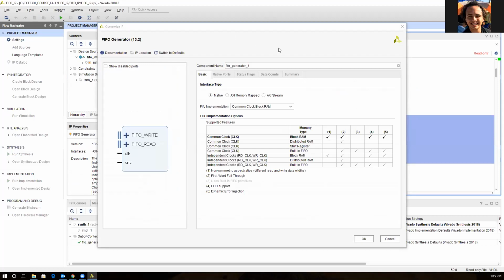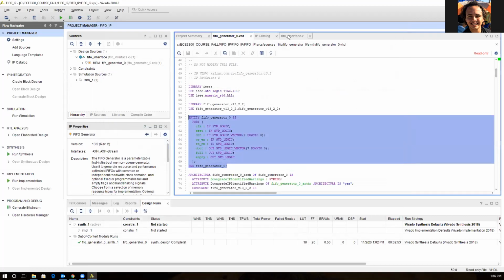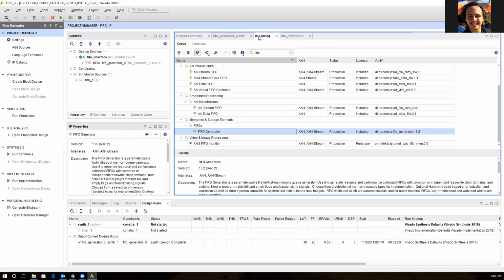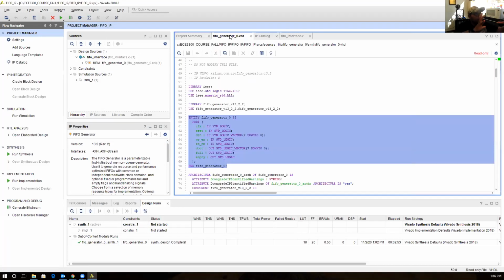If you were to start outside of the IP catalog and then create a block design instead and then add the IP onto the block design? No, that's a different story. You know why? Because you're going to build pieces and connect them together. Still, we are using HDL here, right? What you're talking about is completely different, because you're drawing and placing blocks. Then you have to do something called an HDL wrapper. When you do the HDL wrapper, you return it back to HDL, then you start injecting stuff in the code. You understand what I'm saying? Oh, okay.